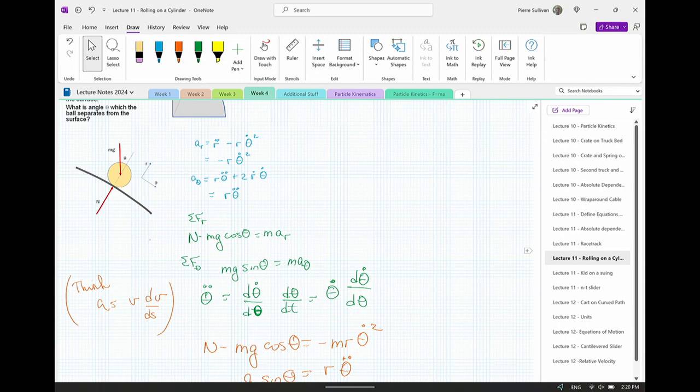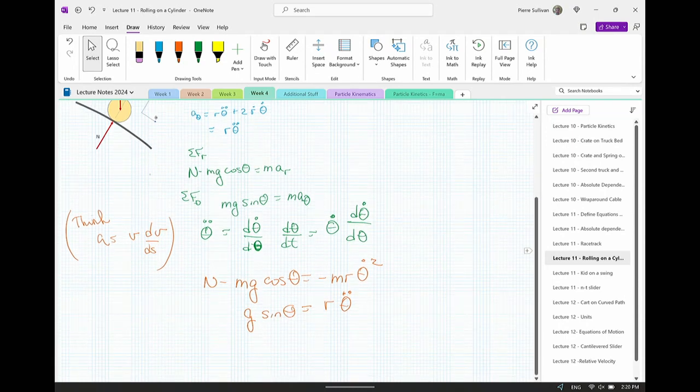And again, very complex looking motion, but once you draw the free body diagram and look at what's happening, there's only two forces, weight and the normal. So as the weight and normal are there, you go on and say, okay, I've got relationships for a, theta, and theta double dot is d theta dt, and I can write an equivalent equation that we will use a lot more in chapter 5, but we'll start to use here for acceleration, which is v dv dx.